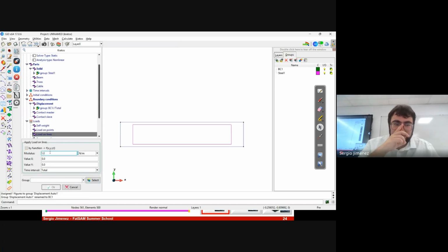Here I have the modulus, and here is the orientation. So if you write here 200, in this line here, you will be applying a load with modulus 1 in the direction 200, 0, which is 1, 0. So the modulus of the load must be applied at this line here. If you apply the modulus here, you will retrieve nonsense results because you are not using properly this section here, or you are not applying properly the load.